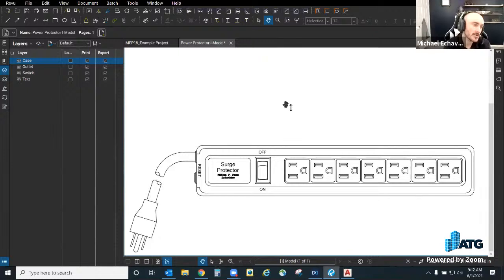There was actually one aha moment I had too. From a DWG you can create it as a PDF where you don't have to open the DWG. The only downside to that is it's whatever view is last saved, however it was last saved, that's how it's going to create the PDF.